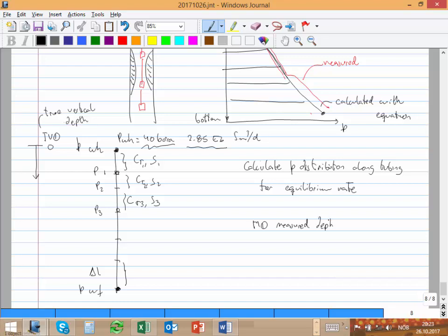So if, for example, the well is deviated and you want to see the MD and the TVD at that point, which one is going to be bigger? The MD. So when they are not the same and MD is much bigger than TVD, that means that the well is deviated. When the two of them are the same, it means the well is vertical.